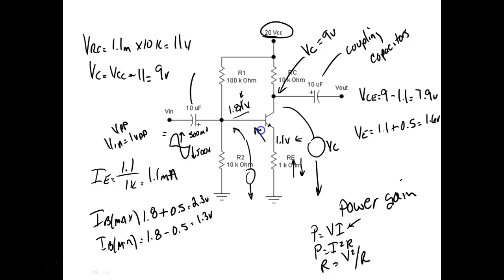So this voltage right here is going to be 7/10 of a volt difference between the base and the emitter, but we've already taken out the 7/10 of a volt when we came over here and said 1.8 and 1.1. So you don't keep taking it out, right? You understand? So what that means is, if this input goes up to 500 millivolts, that voltage on that emitter resistor goes up 500 millivolts. 1.8, you add that plus 0.5. No, we've already got this voltage right here. So this is going up to 2.3 volts.